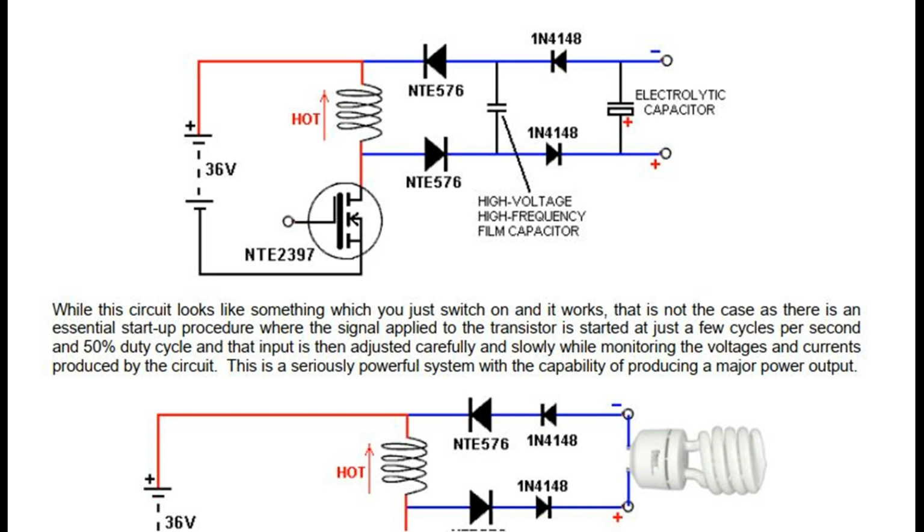While this circuit looks like something which you just switch on and it works, that is not the case, as there is an essential start-up procedure where the signal applied to the transistor is started at just a few cycles per second and 50% duty cycle, and that input is then adjusted carefully and slowly while monitoring the voltages and currents produced by the circuit. This is a seriously powerful system with the capability of producing a major power output.